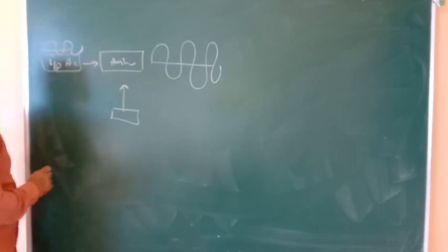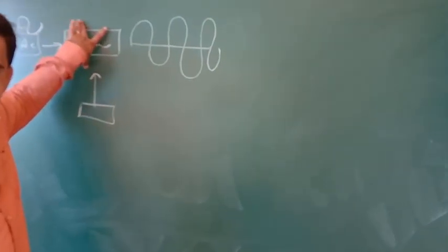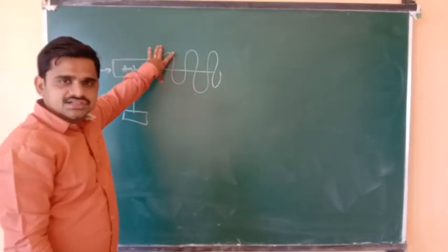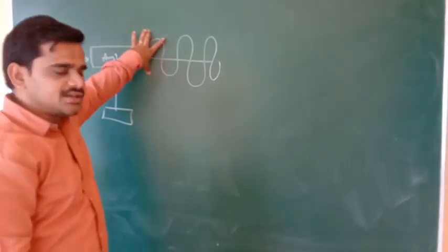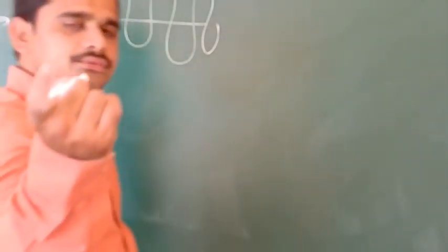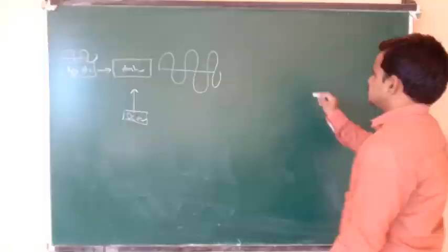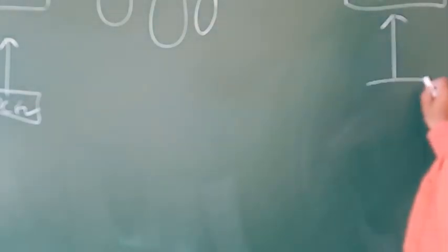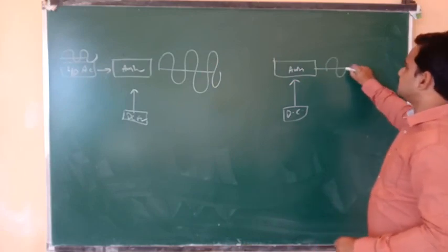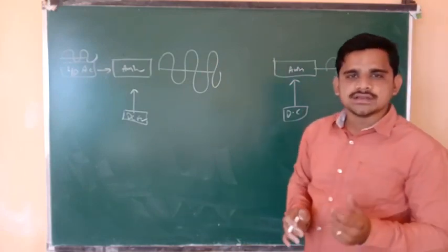Understood here? In a transistor as an amplifier, we are giving some input signal here. To strengthen its waveform, it requires some DC power supply. That's roughly what we are using. Finally the output is the amplified signal, means the strength of the signal is increased. Whereas in a transistor as an oscillator, we are directly giving the DC power supply itself. With no AC input we are going to get the amplified signal. Got the difference here?